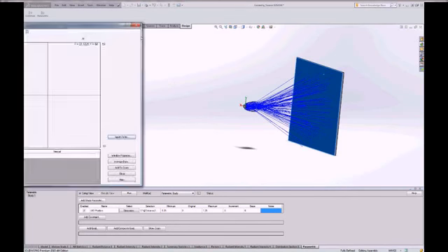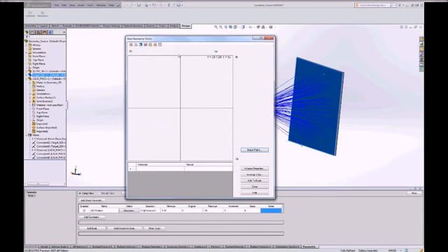Okay. Then you get to define what region of that target you're interested in. You can choose the whole target window, or you can define an elliptical or a circular region. You can define a polygonal region if you wanted. So if you needed to know what a hexagonal distribution would look like, you could enter that as well. You can choose regions, you can define lines, and you can also set test points. So for those of you who are thinking about things like ECE standards, you can enter all of that type of information using the different geometry goals.